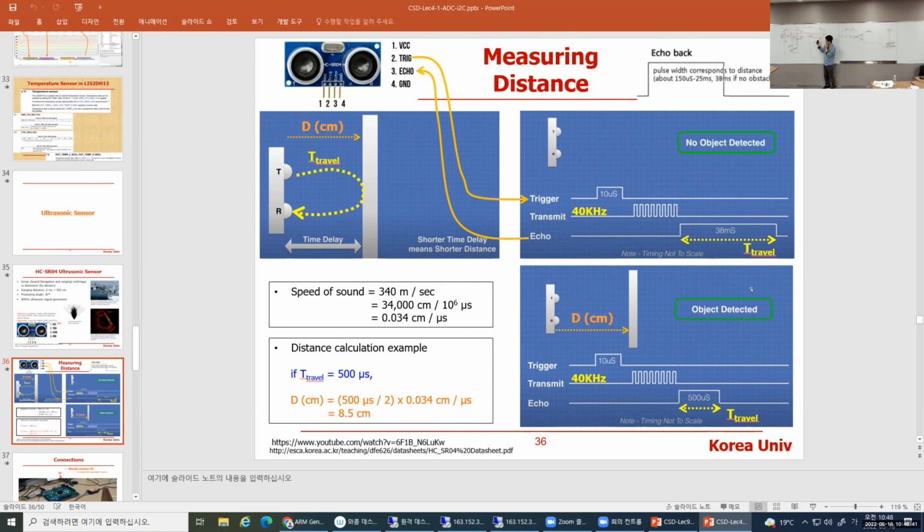But what I want to explain is what would happen if you don't clear that bit. In the level trigger case, the interrupt will be continuously generated, because the GIC recognizes that high level as an interrupt. But if you set it to edge trigger, then it is a one-time generation. If you don't clear that bit, you still have to follow the protocol.